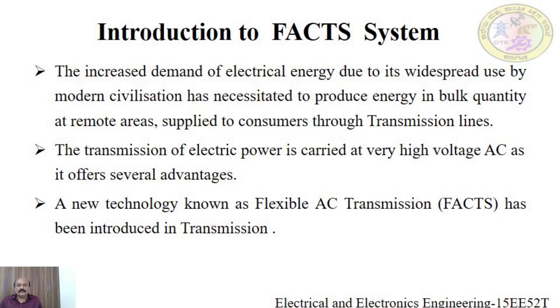On the contrary, at peak load hours, the inductive reactive power absorbed would be more when compared to the capacitive reactive power produced. Therefore, it is continuously varying in nature. This impedance is to be compensated. This may be called as the reactive compensation.